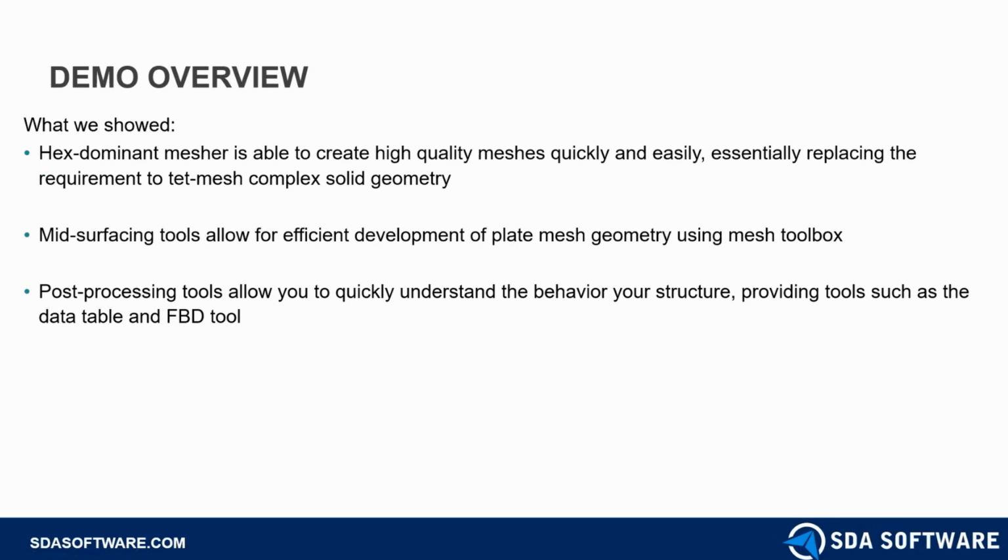So what have we shown today? We've shown how for solid meshes, the hex dominant mesher is really able to create high quality meshes quickly and easily. We've essentially replaced the TET mesh for complex solid geometry in our models. So this is a really powerful tool inside your model for solid meshes.